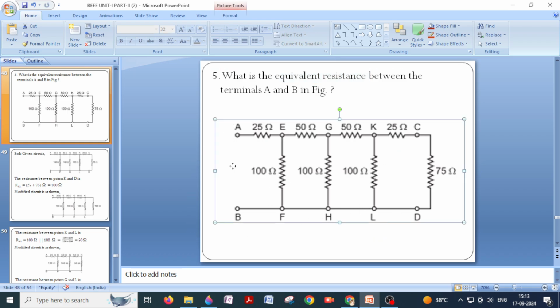In order to determine the equivalent resistance of the given circuit, or the total resistance, across whichever terminals, here across A and B terminals, we have to just look at the opposite side of these terminals. So opposite to AB is what? This side is the opposite side. CD, wherever CD is there, that is the opposite side. Now look at the CD side.